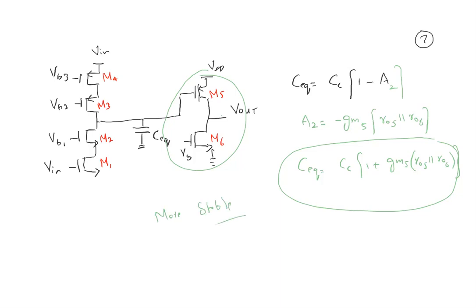So make sure this point is clear, how the system is getting stable. We are ultimately bringing this thing, if previously it was happening like this, we are bringing it like this. Because of moving this, the gain crossover frequency is happening earlier as compared to the previous.